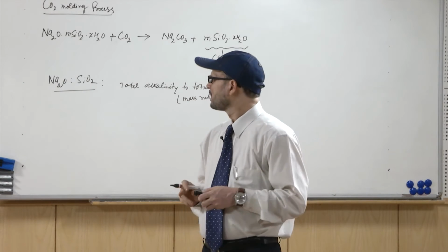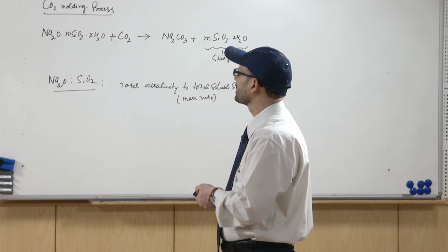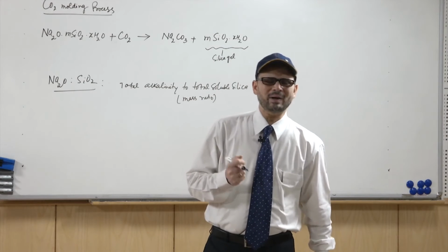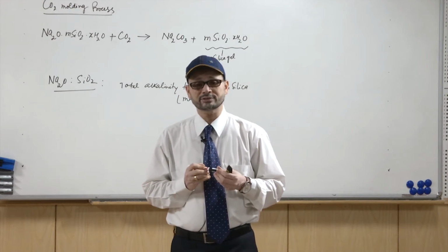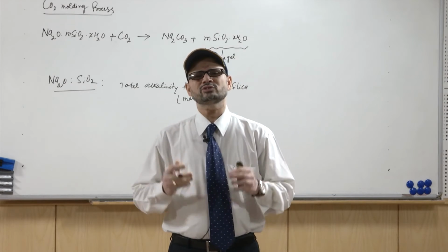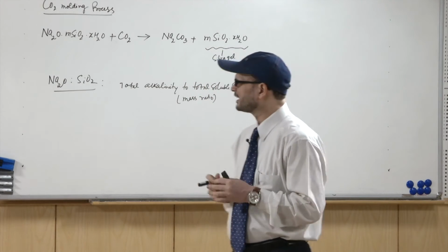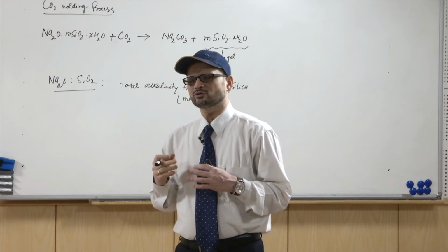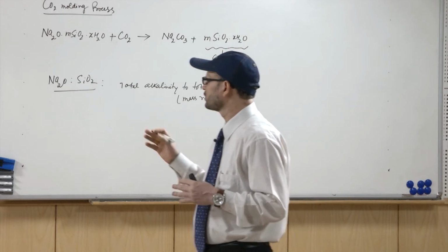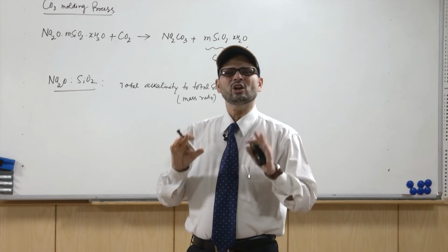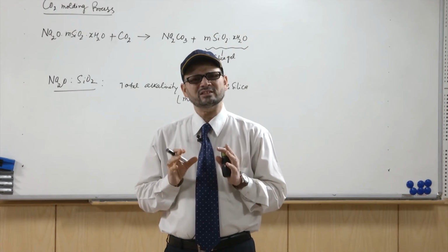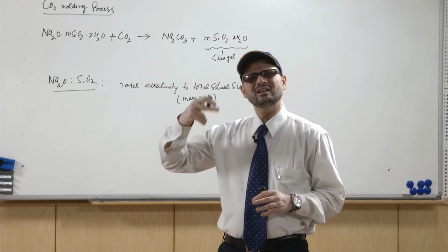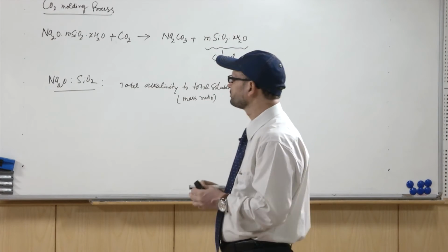In this case, what happens, since you are withdrawing the pattern, because the baking is instantaneous, as you pass the carbon dioxide gas through it, the baking takes place. So, since the baking takes place, in that case the withdrawal of the pattern is better. So, withdrawal of a pattern becomes easy. You need a lower level of skill in this case as compared to that in the case of other processes like using clay as the binder.